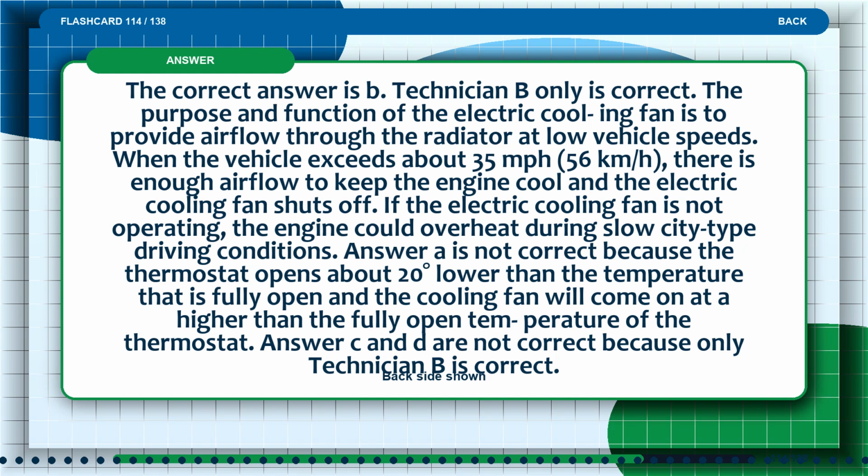The correct answer is B. Technician B only is correct. The purpose and function of the electric cooling fan is to provide airflow through the radiator at low vehicle speeds. When the vehicle exceeds about 35 miles per hour (56 kilometers per hour), there is enough airflow to keep the engine cool and the electric cooling fan shuts off. If the electric cooling fan is not operating, the engine could overheat during slow city-type driving conditions.